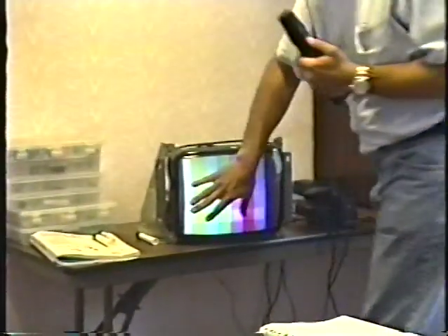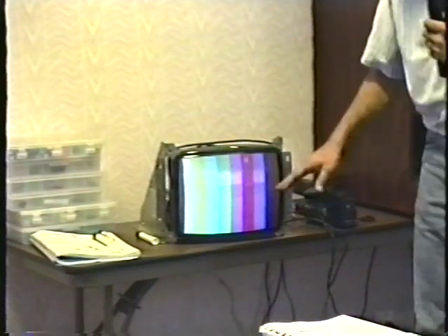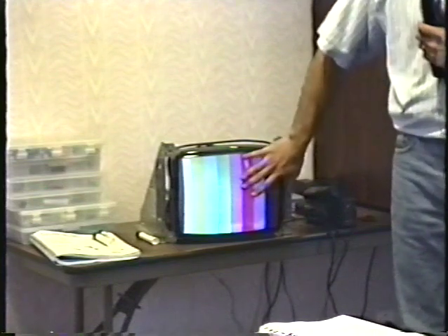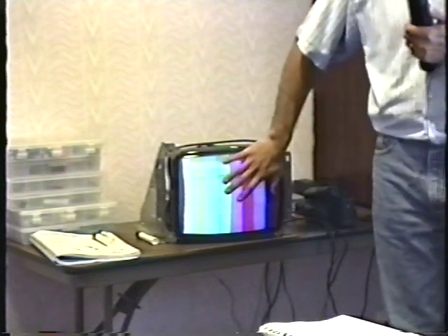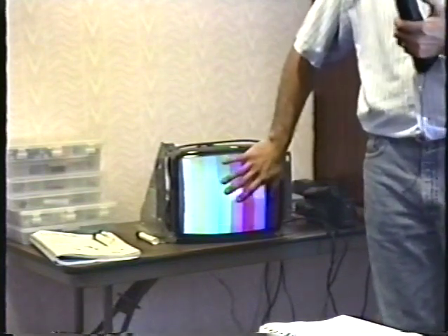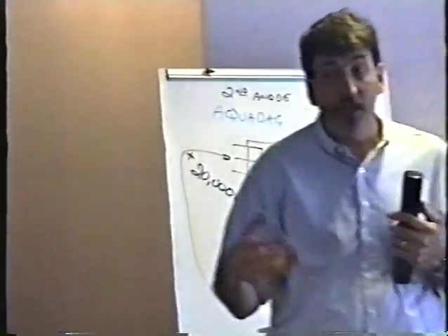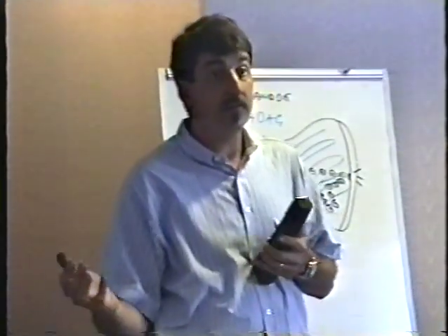But what this also means is that if you see any kind of brightness at all on the front of the screen, and maybe it isn't correct, maybe it's just a line on the screen, or maybe it's rolling or some other problem, you must have high voltage, huh? Because if you didn't have any high voltage, you wouldn't get anything at all on the front of the screen.